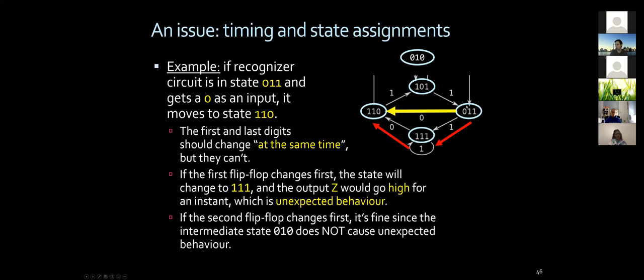So you see, I might jump in a direction I'm not supposed to jump. I might go from here into here, but that doesn't cause unexpected behavior. So this direction, even though it's not in the original graph, doesn't cause trouble. So you see the difference. Asynchrony can create issues, and some of them lead to unexpected behavior, those red lines here, and this one doesn't, okay?